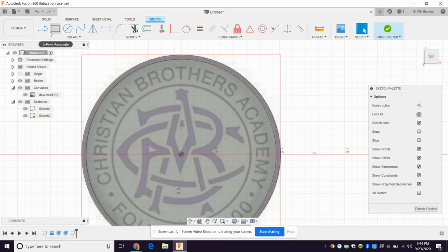So the Brothers logo is actually kind of hard. I've had kids do it over the years. It is fairly challenging. A lot of splines, straight lines. It all depends how you want to do it. I've done it before, one piece at a time. You know, it's not snapping to the grid, which is good. I guess I turned that off. I'm just going to do straight lines for this part. Starting to want to snap to things, so I'm going to hold down Control. Yeah, that still works. Control still prevents snapping. It snaps too much.